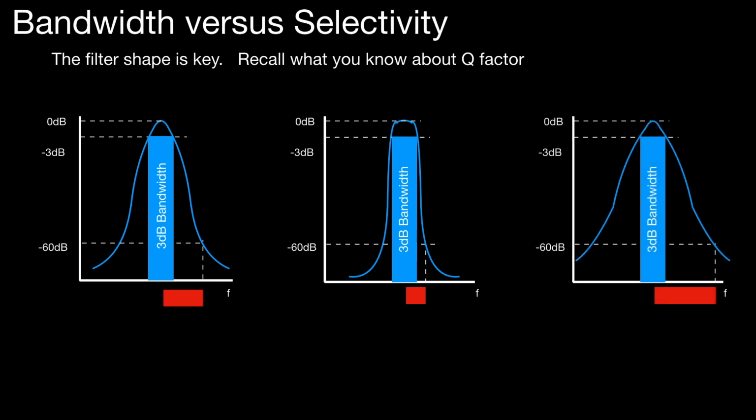This graph here, similar sort of graph, but here we have a much sloppier curve. You can see there that the bandwidth remains the same. Across the top it's not very linear between the two 3 dB points, and at the bottom the selectivity is quite wide. So if you were going to purchase a receiver with one of the characteristics, the best one to buy would be the one in the middle, then number 1 on the left, and finally the one on the right.